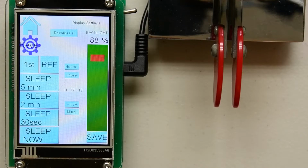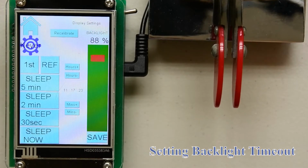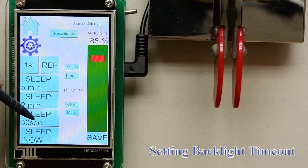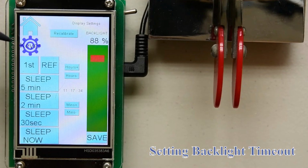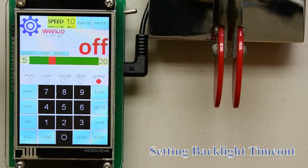The sleep buttons control only the backlight of the display, and have nothing to do with the Arduino Mega 2560. So if you're operating portable on batteries and need to maximize battery life, you could, for example, set a sleep of 30 seconds and then go back home, and after the display blanks, the Arduino is still active so that you can still use the keyer even though you can't see anything on the display.